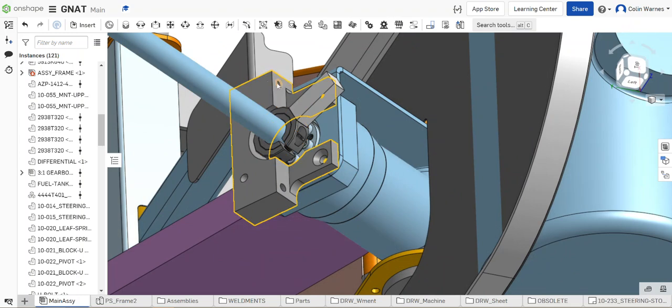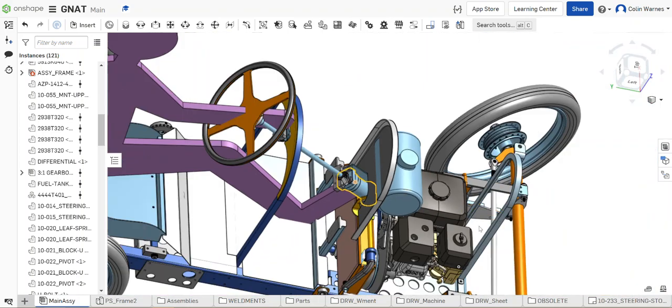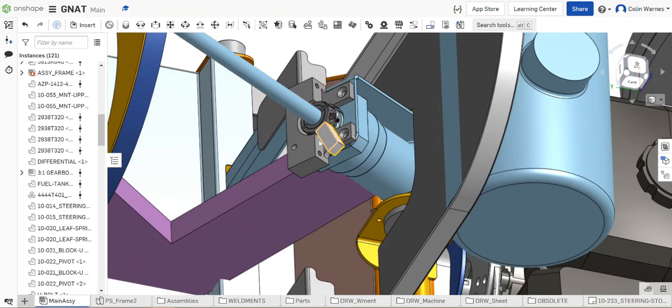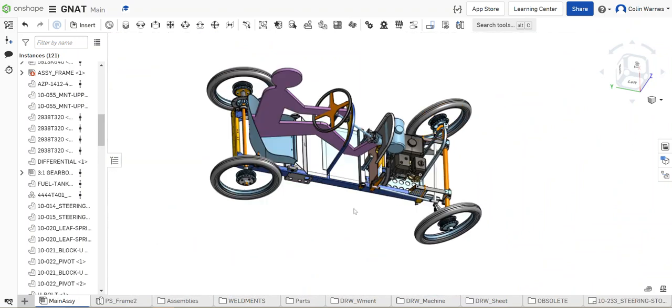There'll be either set screws or bolt heads that come through here. Basically, they will limit the steering to 135 degrees of motion, which matches the steering limits of the wheels. So when I turn the wheels, they'll hit physical stops here, and as a secondary stop, I'll have the steering knuckle stops.